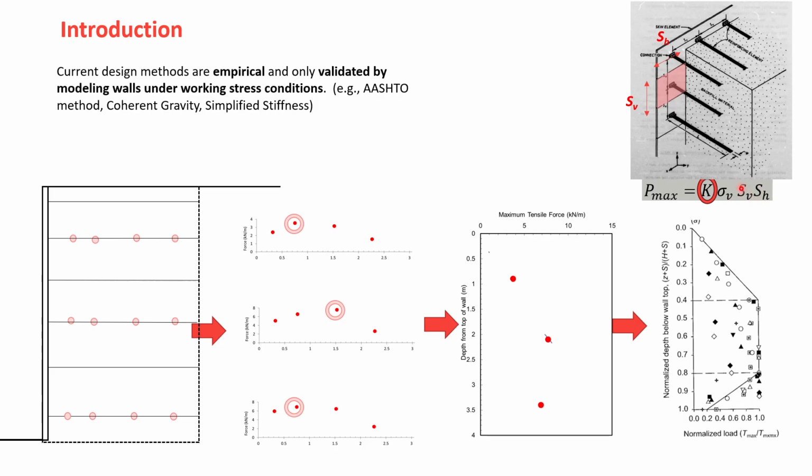So you have a vertical effective stress, and then you have the area, which is the tributary area you are concerned with if you are designing a particular reinforcement. And then you have a K factor. K is the lateral earth pressure, which, to be precise, is in fact not an earth pressure, but was derived mainly from instrumented walls. That's something we sometimes overlook.